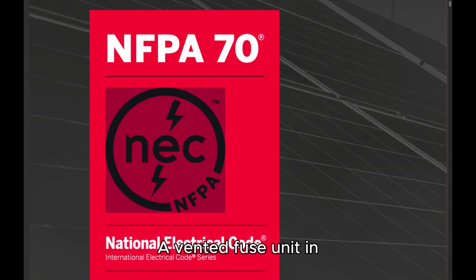A vented fuse unit in which the expulsion effect of gases produced by the arc and lining of the fuse holder, either alone or aided by a spring, extinguishes the arc. Non-vented power fuse. A fuse without intentional provision for the escape of arc gases, liquids, or solid particles to the atmosphere during circuit interruption. Power fuse unit.